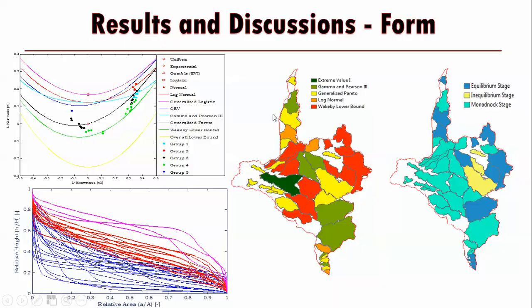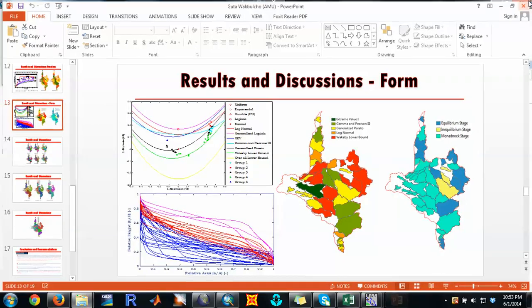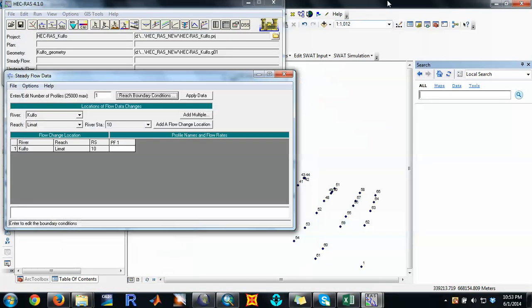Based on that, once you find these, you have to estimate your parameters by using one of the approaches like the maximum likelihood, the conventional moment approach, or the probability weighted moment approach. From that you can fit your flood with several return periods.